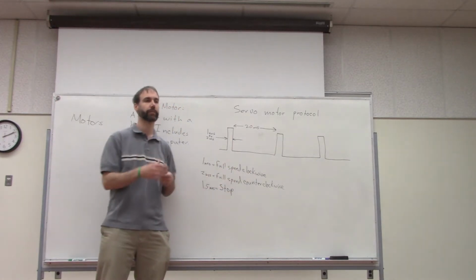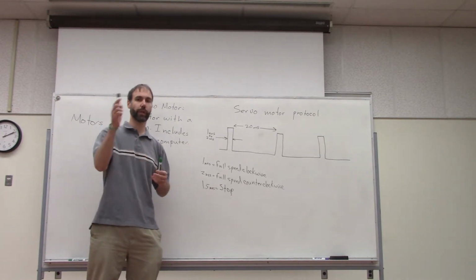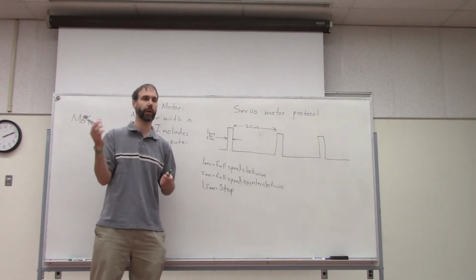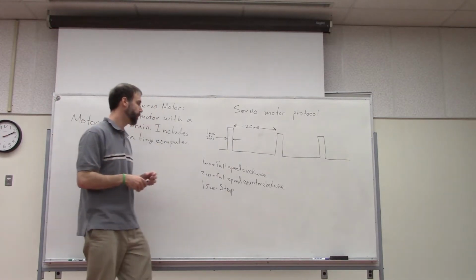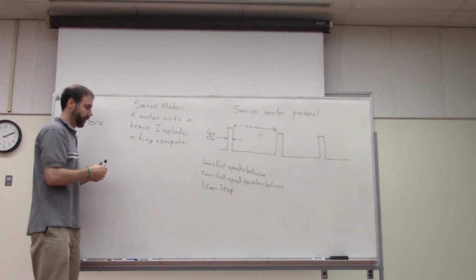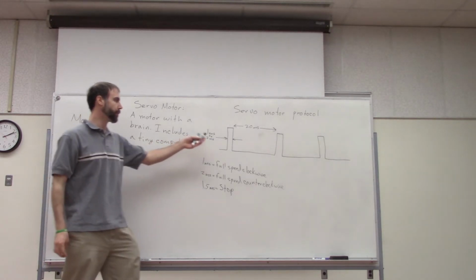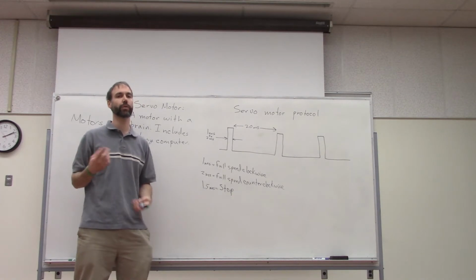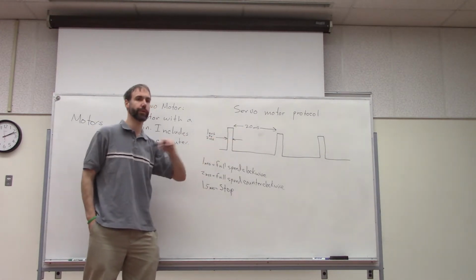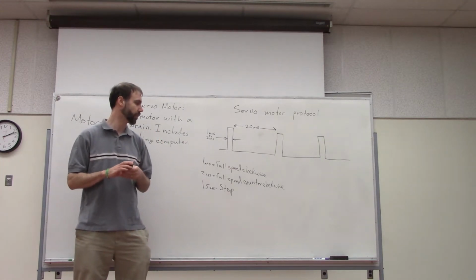So that would control both motors? No, this is just one motor controlling 2 directions. It can either turn in one direction or turn in another direction. So each motor has a little cord that accepts these commands. So if you had 2 motors that you wanted to control, you would have to send out this type of command on 2 different pins. Yeah, so we'll see that in a little while.